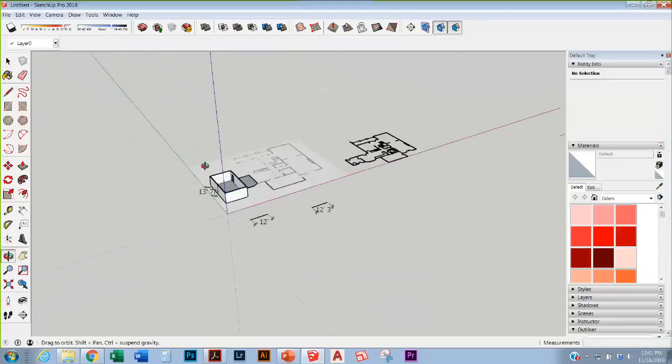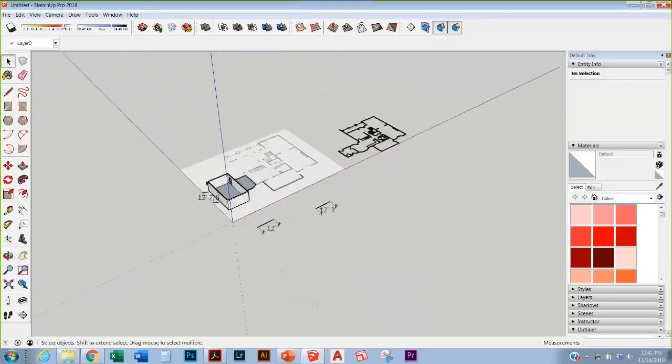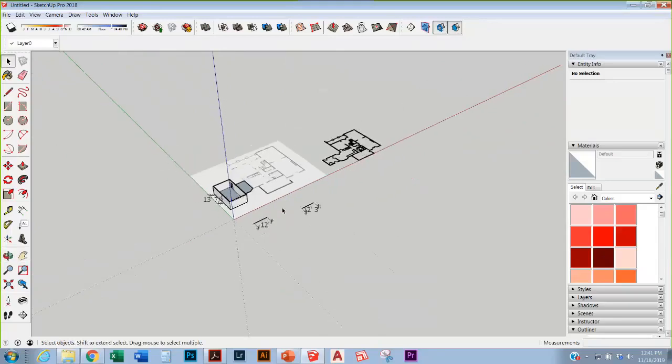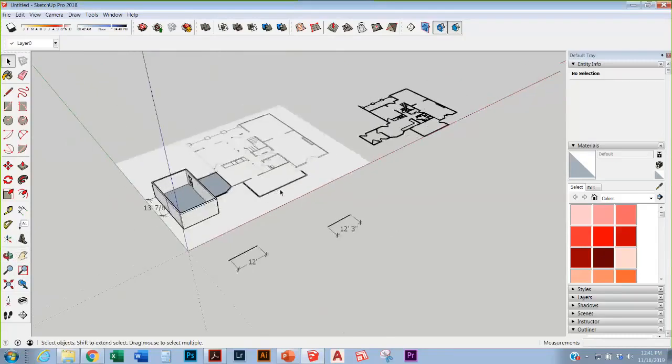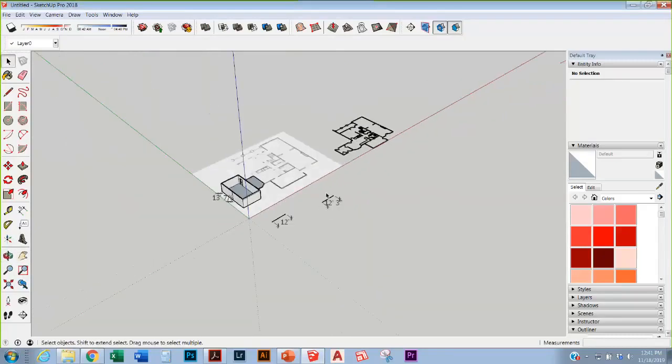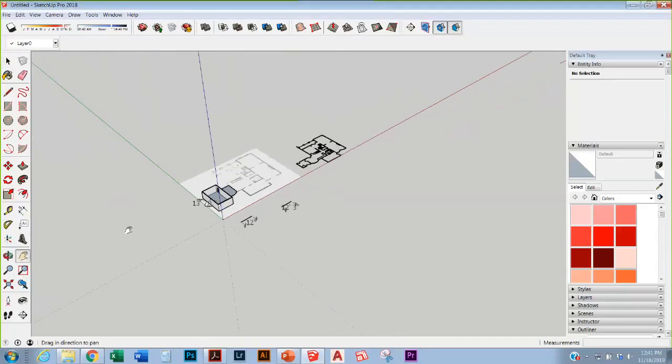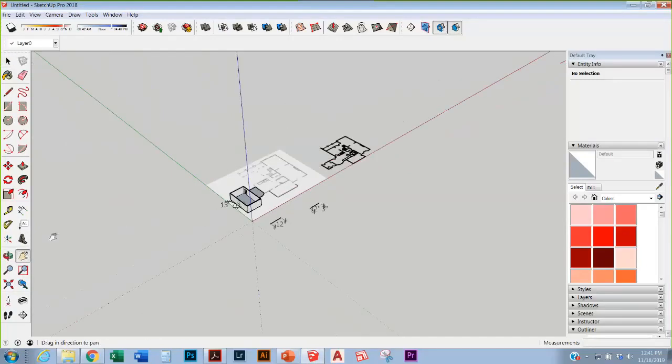Again, rotate is that second button, and then you can use the pan by holding down the space bar, as well as the center wheel on your mouse. You can change your settings on your mouse to do different things, but definitely you want to have pan and rotate as hotkeys on your mouse. That allows you to really navigate easy. And of course, your mouse wheel in and out does your zoom. So rotate, zoom, and pan right here allow you to effortlessly maneuver.